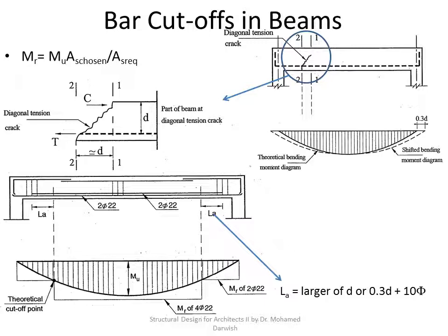And because of that, this is the point where, theoretically speaking, you could have the end of the cutoff. So I could simply cut the steel here. But do I cut it here? Practically, no. I need to move a distance beyond this point.